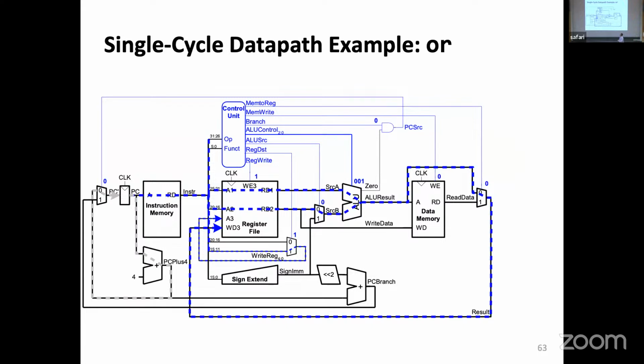Now, we could extend the operations. You know, we can have OR, and in OR, the program counter reads the instruction, realizes OR, picks two operands, goes through the ALU, ORs them together, jumps over the memory, and the result comes back here. The address to write back is being calculated here. This guy says, pick this one, tells it, and then we are done.